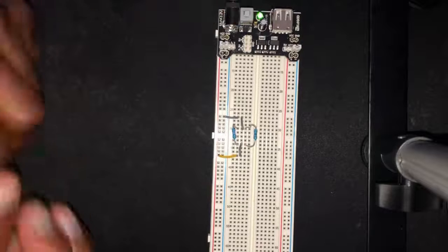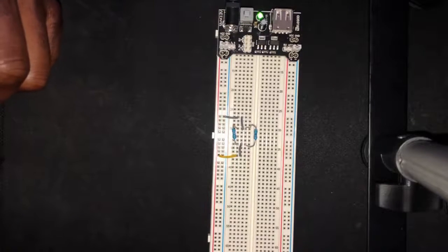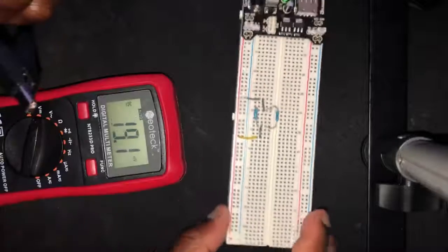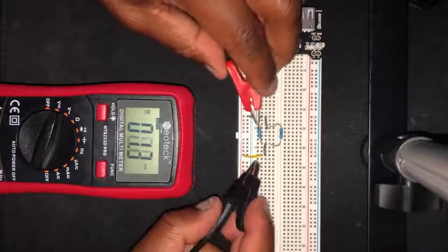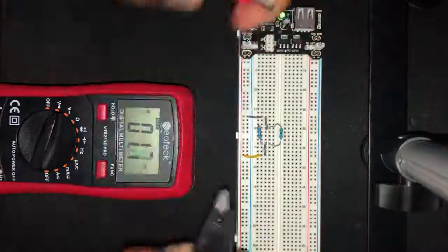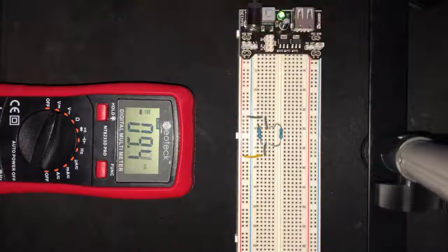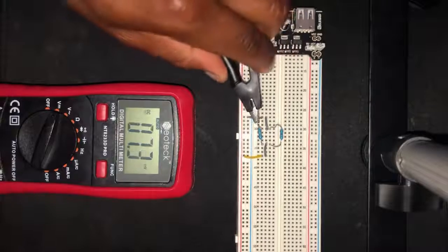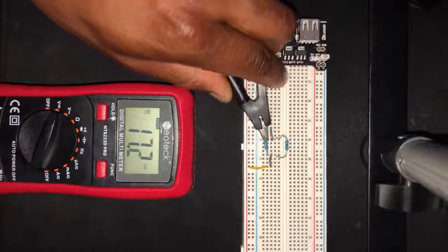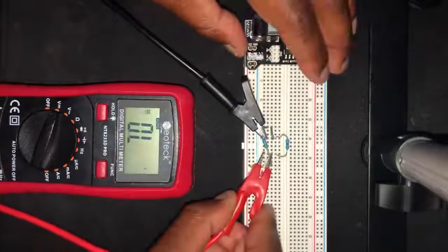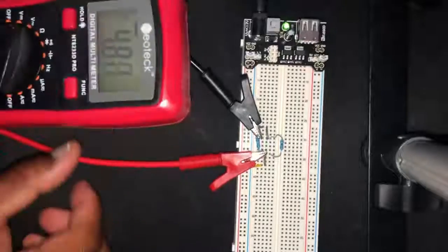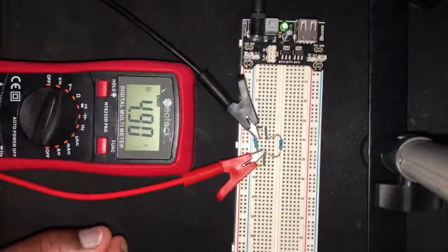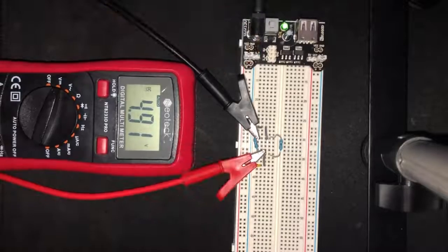So let's switch this circuit on and let's measure. So set this to measure DC voltage. So this is the 200 ohm resistor, I think. Doesn't really matter. We should see about 5 volts on both of them. Okay. So I'll just place that there. Place that there. So 4.88 volts. Why are we losing a bit of voltage? Well, because this is an imperfect circuit. So the wires